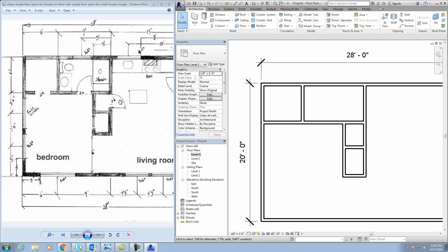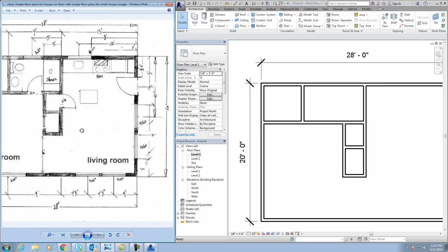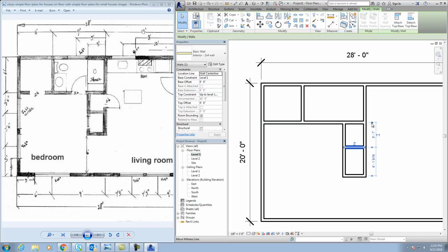Now there looks like a door of 26 inches. I don't have a measurement, so trying to see if I can spot one. That's going to the center of that window. So I really don't have a dimension, so it must be closets. So we're just going to throw in a number here, and I'm going to show you a cool thing. I want to center this thing up and have these closets equally spaced. Click on this, and you see this little button right here? If these are temporary dimensions, when you click on them and they come up like this, if you want to make them permanent like these, you click on this button right there.